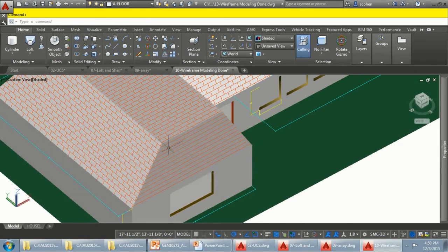And to draw the roof and everything else, I just changed my UCS here and drew a hexagon. Then I basically just snapped lines, literally, and then I hatched when I changed my UCS to here. Changed my UCS here, hatched here. That's all that you do. You just change your plane, and this didn't take me long. It probably took me 25 minutes.